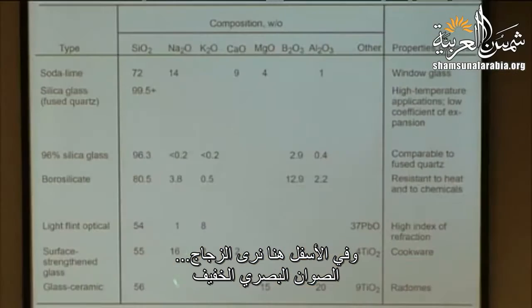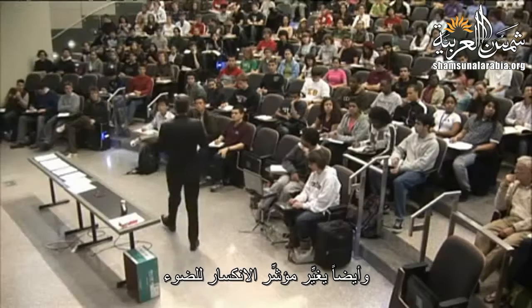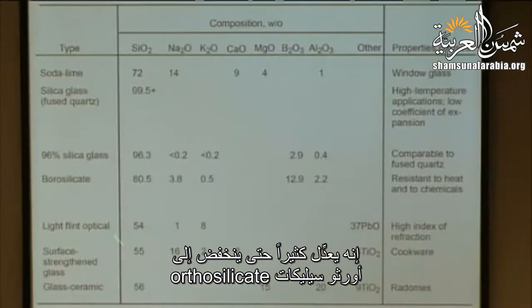And down here, we see glass. Let's see, here's the one, light flint optical. See, that's 54%. It's down to 54% silica. And look at this, boatloads of lead oxide. And the lead oxide is acting as a modifier, and it also changes the index of refraction. It modifies so much that we have almost down to the orthosilicate.